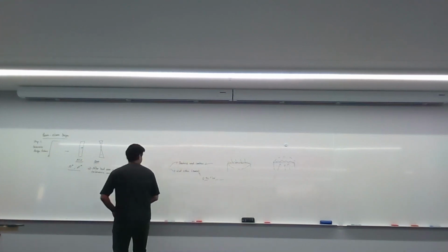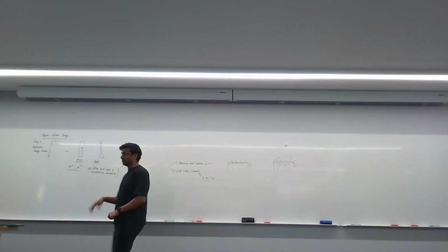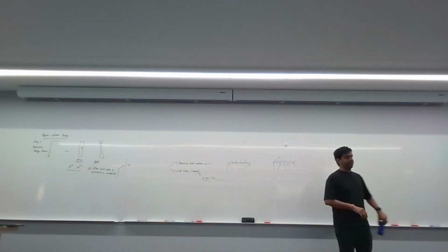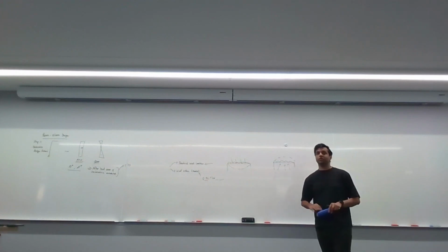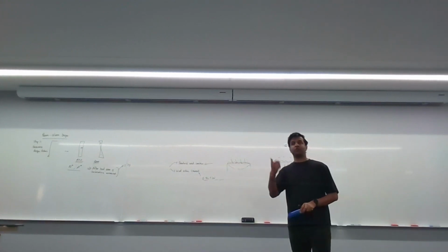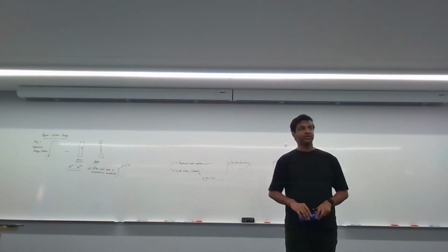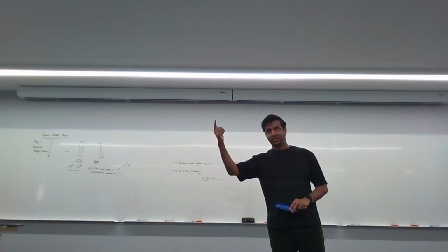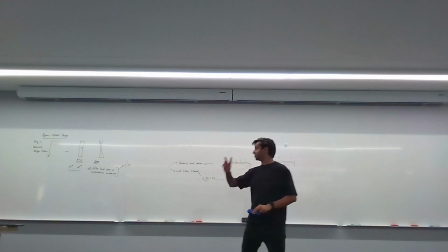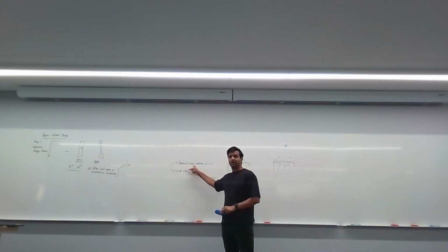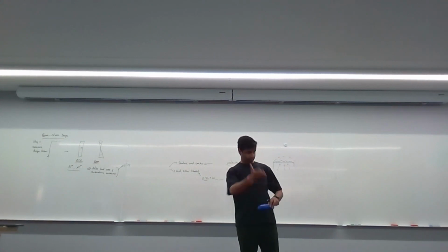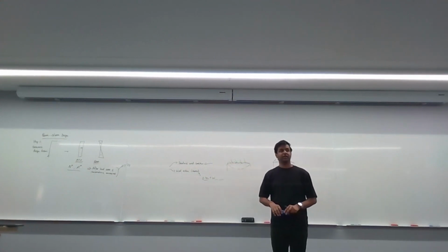Okay. So anyway, that's an important point that I want to draw to your attention. Make sure you don't miss out on any load combinations. So for example, if you have dead loads, live loads, and a wind load, what are your load combinations? 1.2G, 1.5Q, 1.35G, and then you've got two wind combinations, standard wind condition and the wind action reversal. So you go through all of these and pick out the worst case scenario, and that's the one that you use.